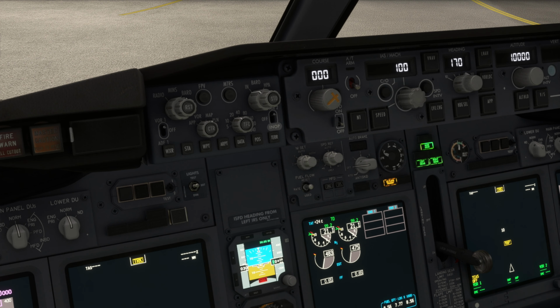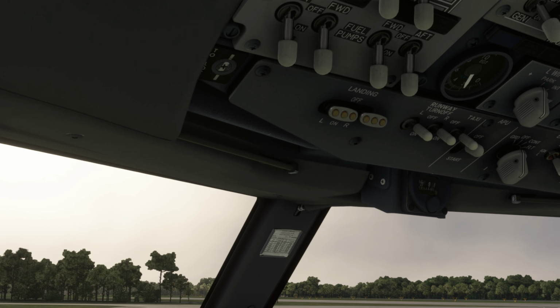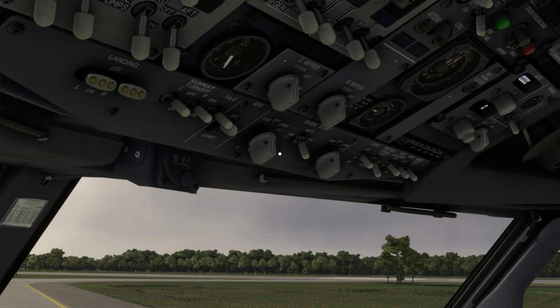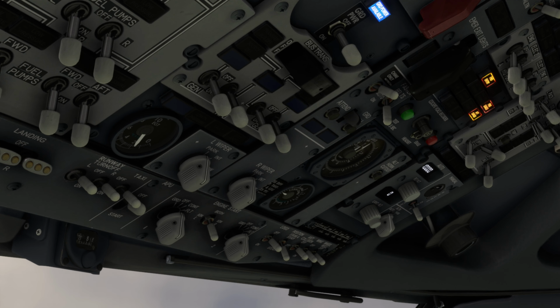On the 737, it's actually somewhat interesting because we don't have landing gear doors. We have the main gear, which just fold up into the fuselage. The nose gear does have doors, but the main gear do not have any doors because the airplane sits rather low on the ground. But we don't have the landing gear doors open on the nose gear. We don't have any evidence that the landing gear has attempted to deploy either via hydraulic or gravity actuation, which is the reserve emergency means by which to deploy the landing gear.